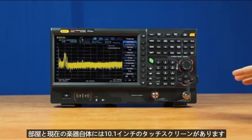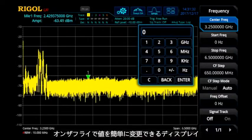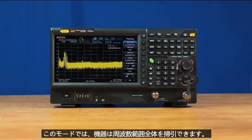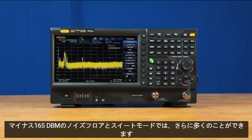And then the instrument itself has a 10.1-inch touchscreen display, which allows us to easily change values on the fly via the touchscreen, or we can use our more traditional soft touch keys themselves. In this mode, the instrument can sweep the entire frequency range for this model in 1 millisecond. And this instrument comes with 1 Hz RBW and a noise floor of negative 165 dBm.